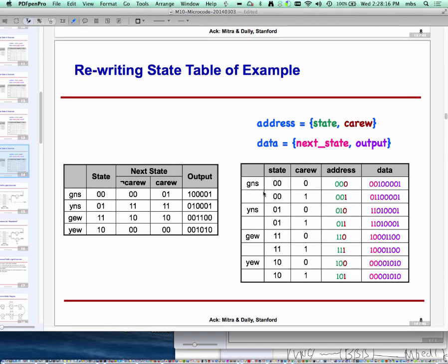See out here how for each state, I have multiple entries in the memory, one corresponding to each of the two values of the sensor. So my state was 0, 0, but in the memory, I needed two entries, one where the input was 0 and the other where the input was 1. Right? So I actually have number of states multiplied by 2 to the power number of inputs. Whereas with the whole branching approach, I basically need as many entries as the number of states.